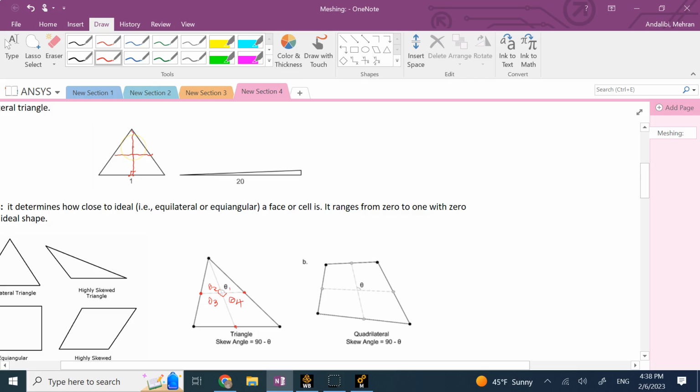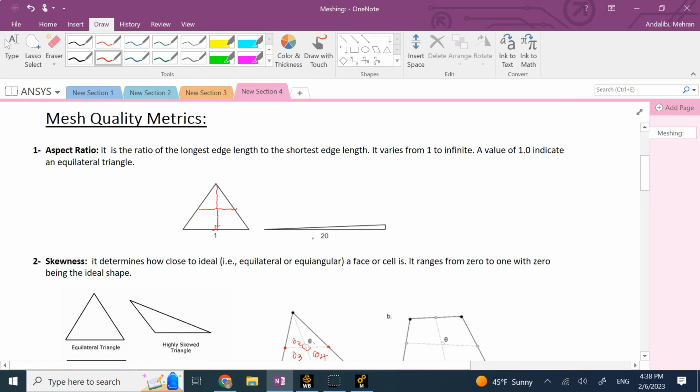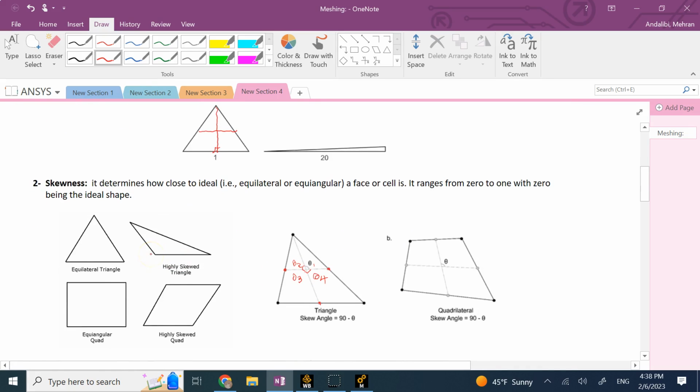Which means perfect. Now, the more this triangle is skewed, the more it is turned to one side, the more these angles would deviate from 90 degrees. You clearly can see here that I have two angles that are more than 90 and two that are less than 90. So when I calculate this absolute value of 90 degrees minus all of these theta i's, clearly your values are going to be non-zero.